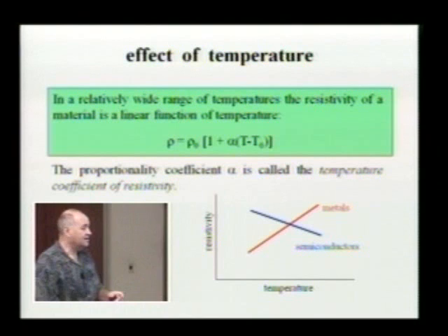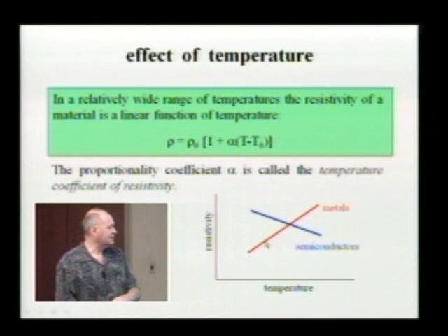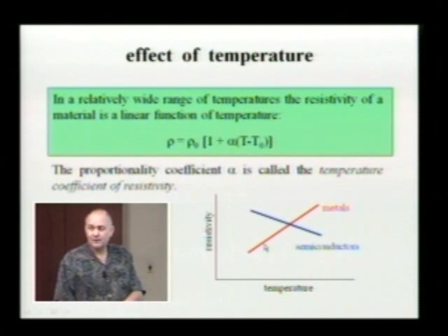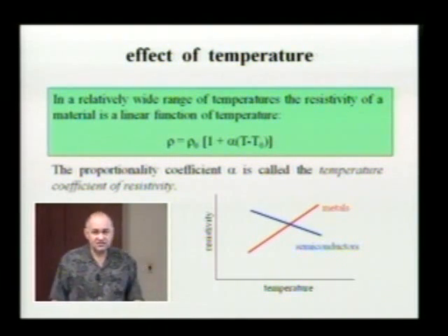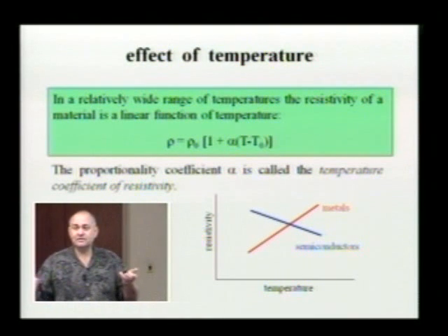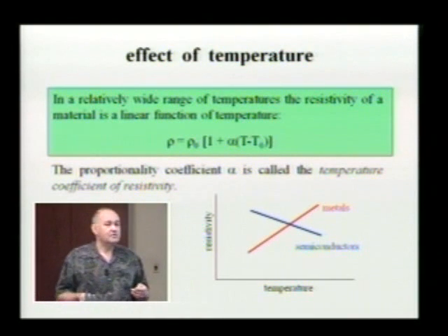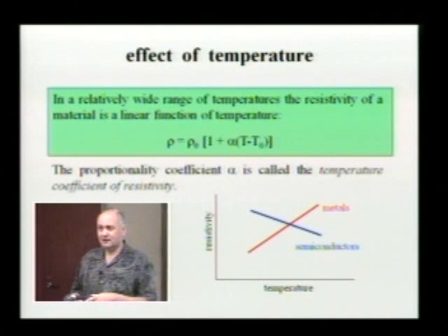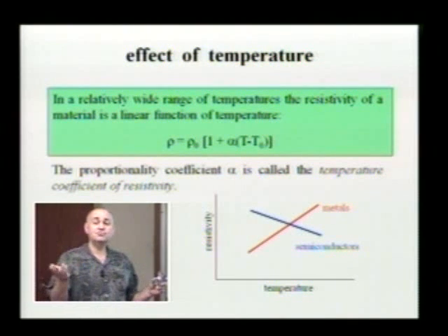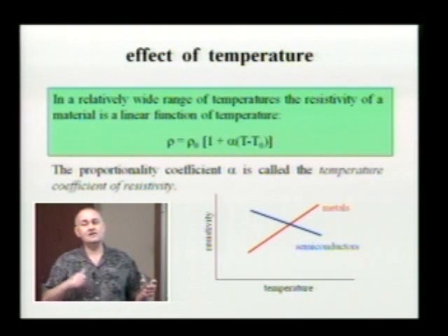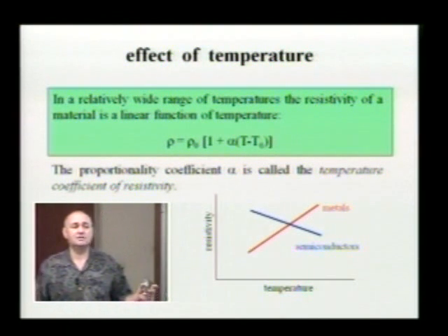Tungsten is a metal, so at lower temperature its resistivity is lower than at high temperature. Therefore, when that wire is cold, the resistance is also lower than when we turn it on. Which means that when I switch the light bulb on, the initial current has a higher value or lower value than during normal operation?